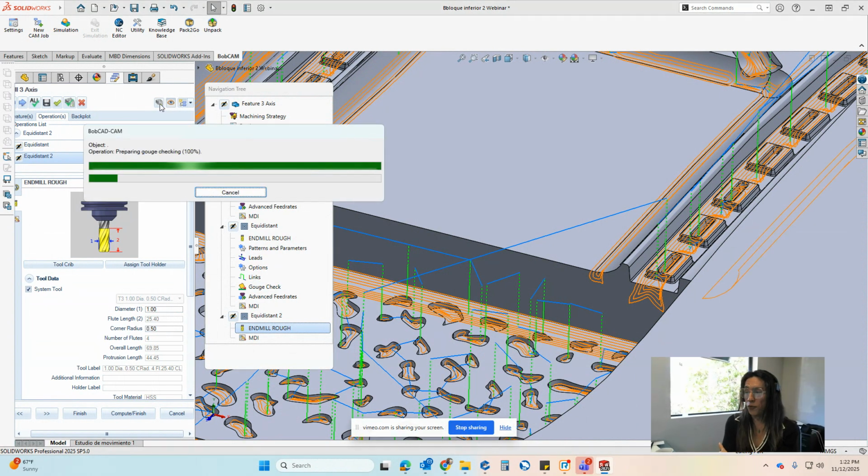Again, the trick of making these changes is to always have a toolpath present. Don't try to do this operation as the first operation because it's going to take longer to process. But if you have a toolpath already present, it builds, like I said before, from the prior toolpath. So just do a simple one and then apply the more complex operations to your toolpath as you go, like we're doing today.